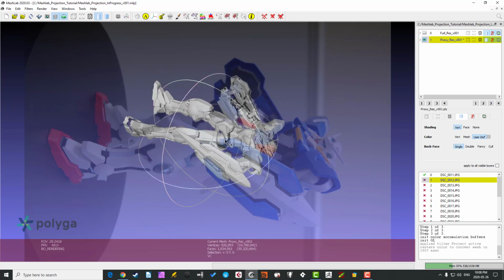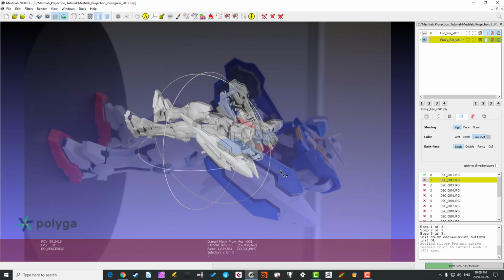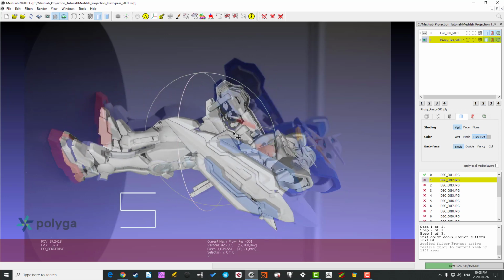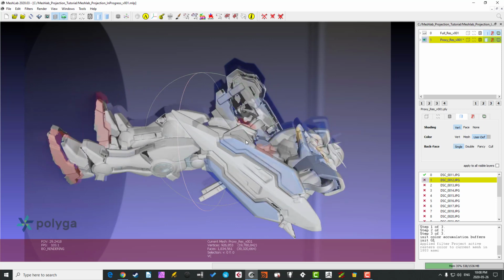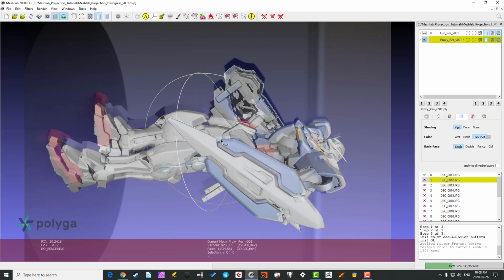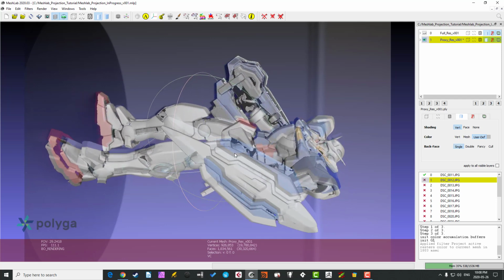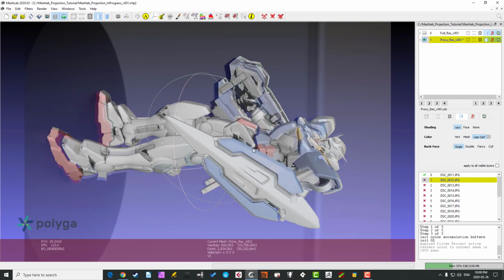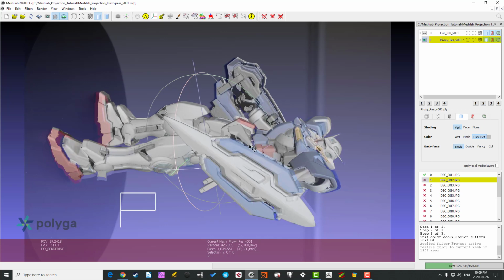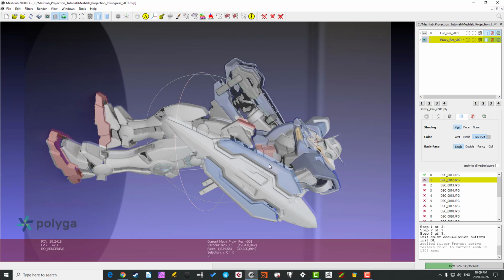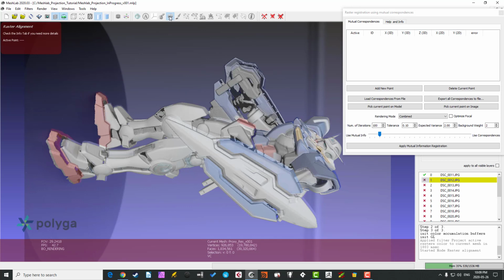Remember the Show Current Raster mode and Raster alignment buttons on the toolbar. As a hint, pay attention to the negative space in your silhouette. I found this really helped me with quickly lining things up. Also, if all of your photographs were taken using the same lens, keep that in mind when you find a field of view that works for lineup, and start from that for each photograph. When you're happy with the lineup, don't forget to snap the projection using the raster alignment on the toolbar.